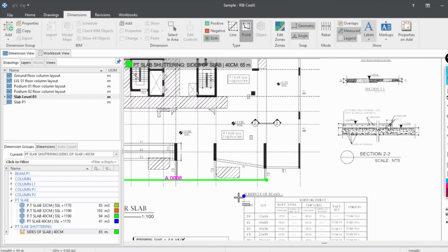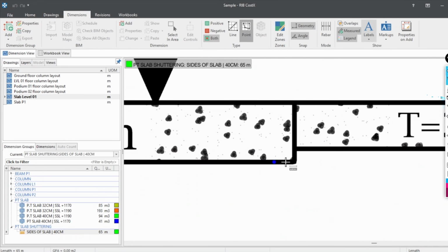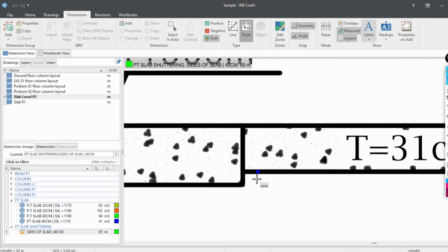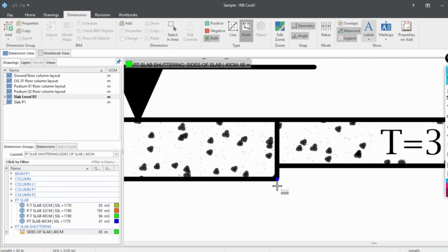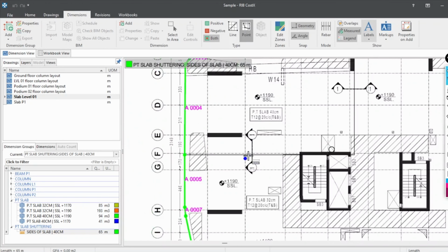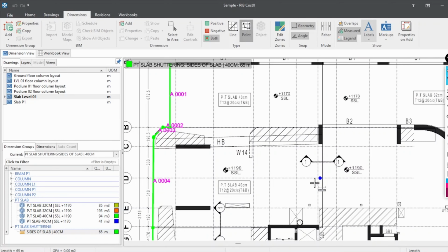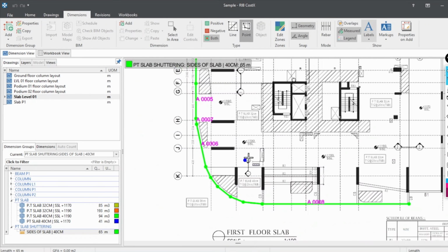Now coming to another part, which is the drop. The simple concept is wherever the concrete is exposed against gravity, we have to provide the support or shuttering to that area. With that concept, here we have the 8 centimeter drop. So wherever the section 1 is there, we have to provide the drop shuttering, and mention the drop shuttering.